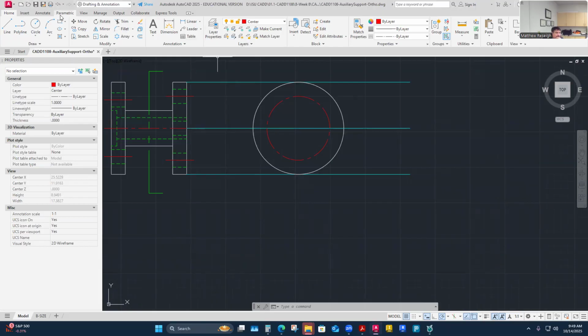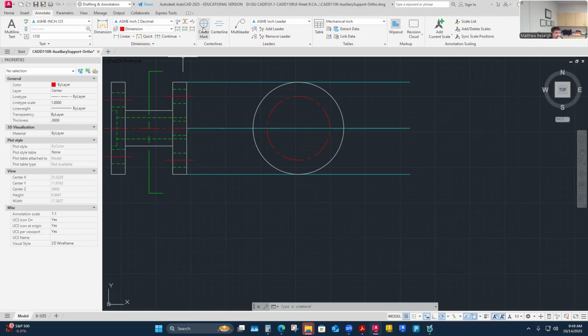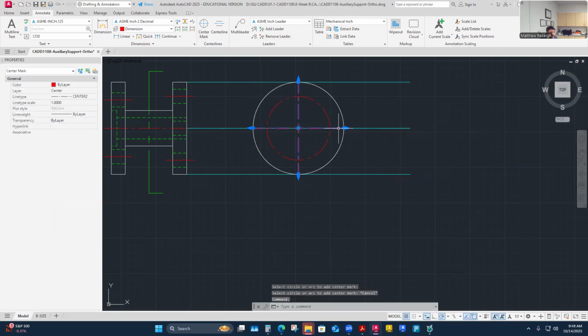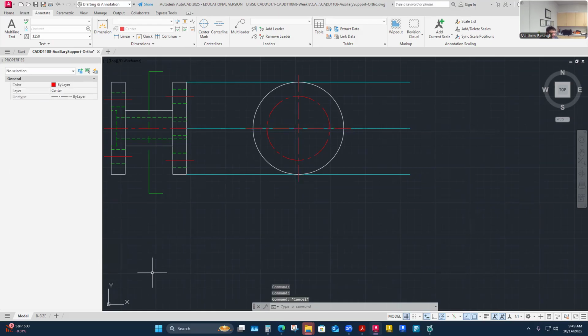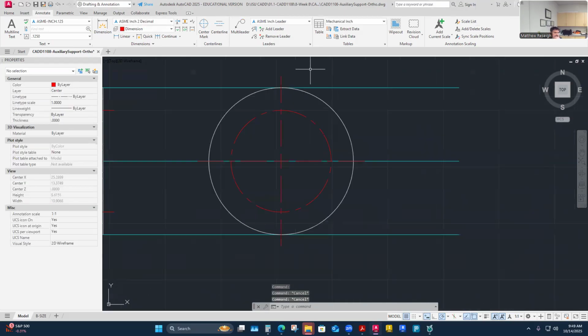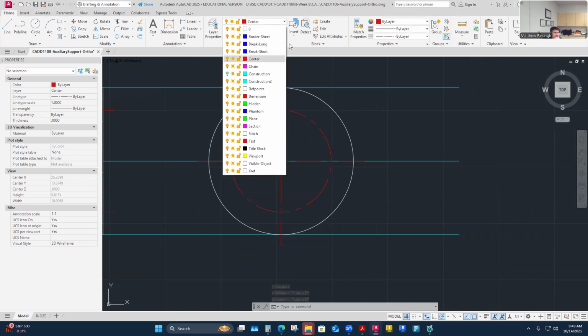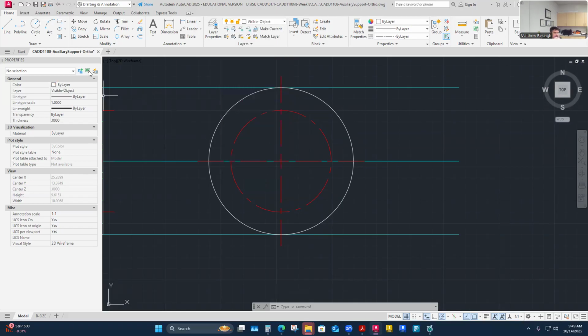And then like yeah, just like Sky mentioned the first time I did this, I can do a center mark on this that shows the intersection point. I can customize that to be ASME standard center mark. And that gives me a place to do the next circle as well. So I could project those over, but I think I'm just going to draw them now that I have everything that I need right there. They're 1/2 inch holes here, so that's a 1/4 inch radius, 0.25 or 0.5 for the diameter.